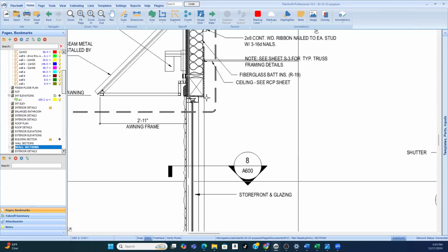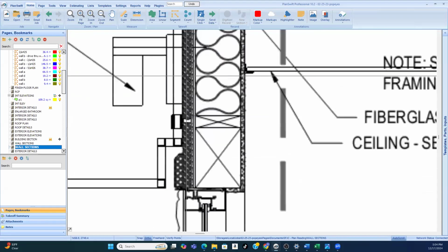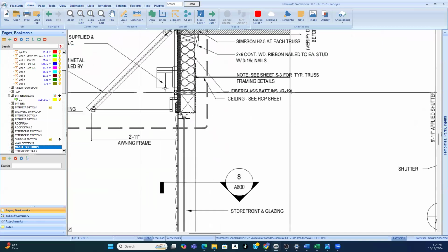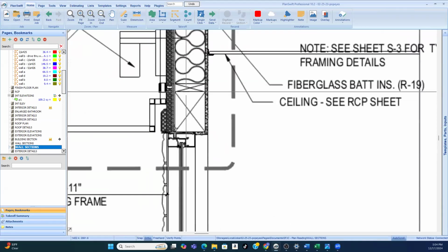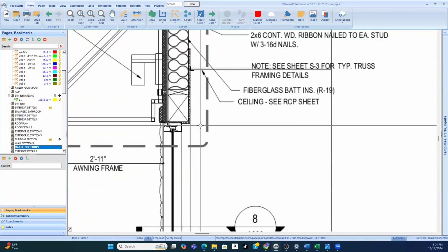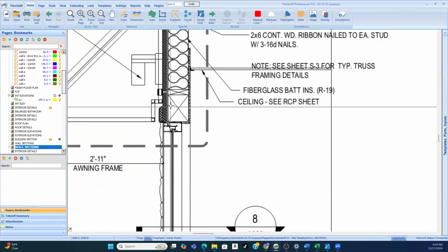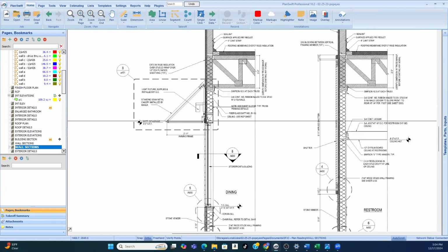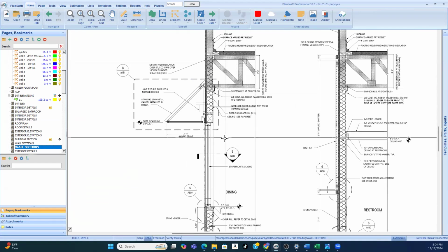And also the tops of every window, right? Those are headers and beams. So you see that they're represented here. There's an X. We know that's a beam, and we know that that's 2x6, because the walls are 6 inch, and we know that's a structural beam, but there's nothing on it telling you the size of it, other than we know it's wood. Why? Because above the windows, above the doors, that's structural framing.